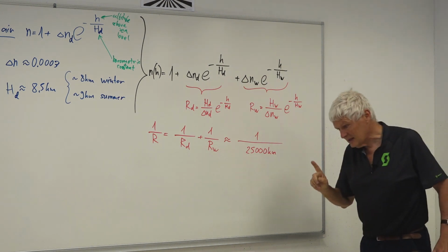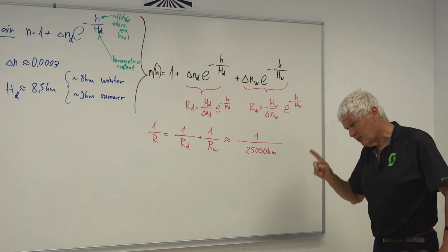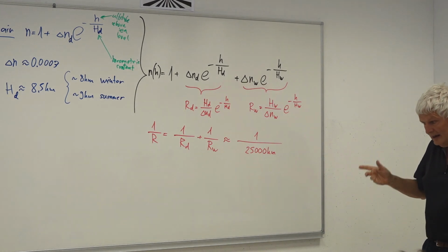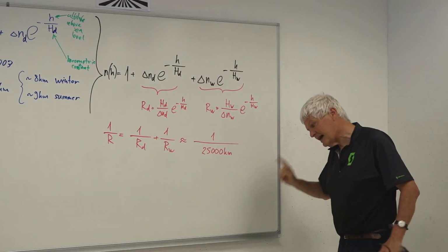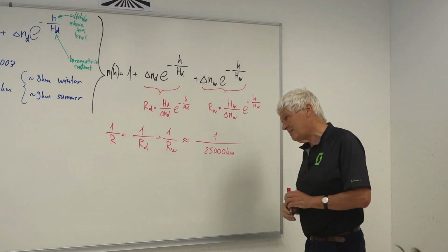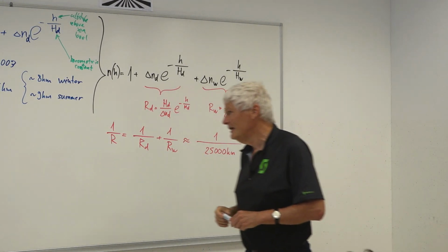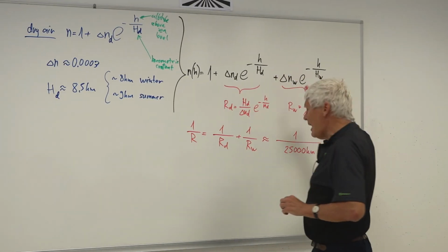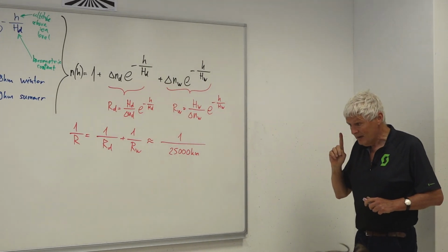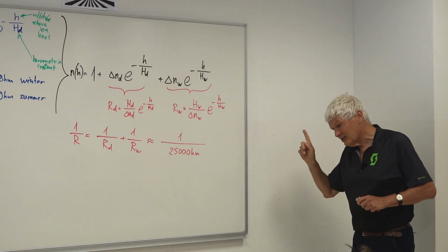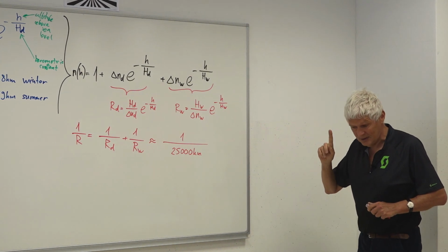Summer is wet because the saturated pressure of water vapor in air increases very quickly with temperature. The warmer the air, the more water vapor it can take. And here we are only interested in absolute values of humidity, not relative values. Remember that the weather guys on TV only talk about relative humidity.